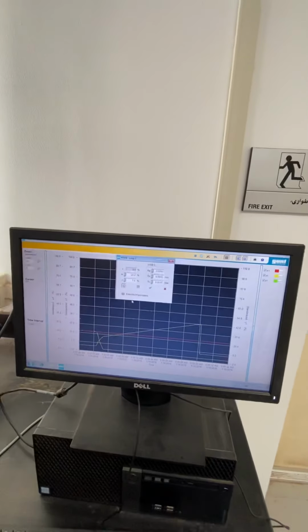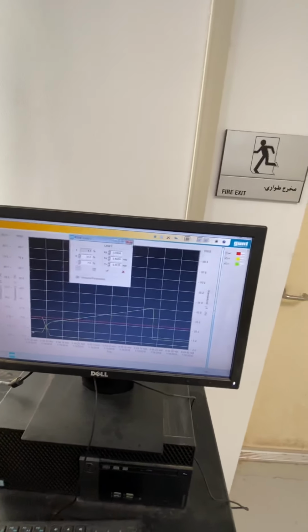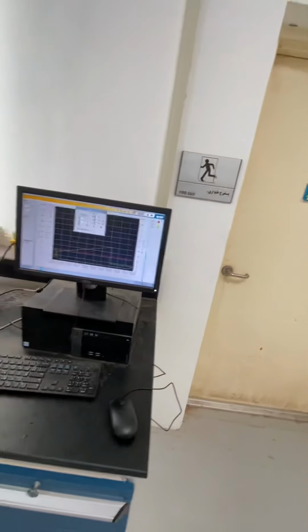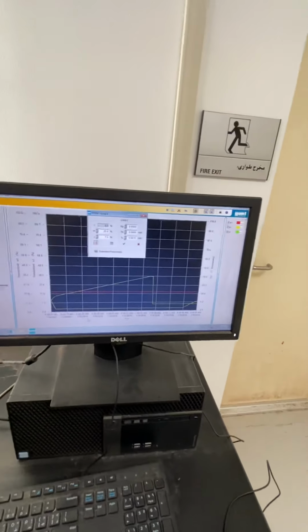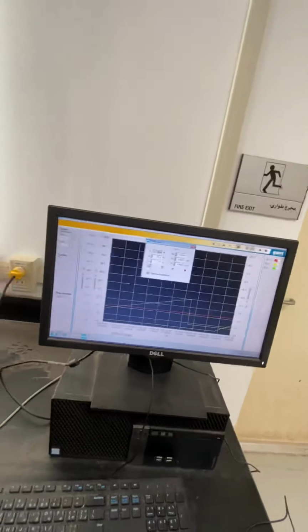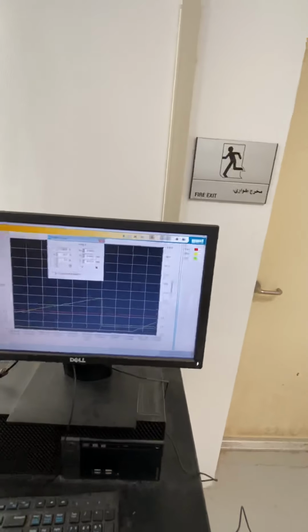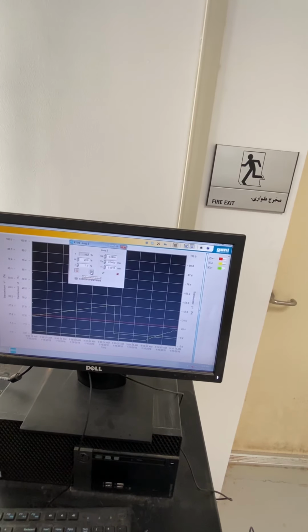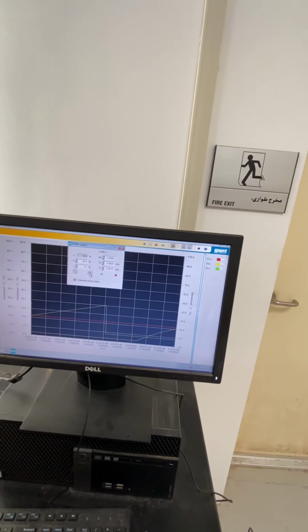I'm doing this manually, guys. You can see that if we have an emergency in the system, we have to switch to the manual mode. And from the history of the process, or the trend, we will try to see what the output signal was before the problem happened. So it's basically the output signal for the last good PV. As you can see now, the system is returning back again. Let's give it a few seconds and then try to switch to the automatic mode once the measured value is matching the set point.